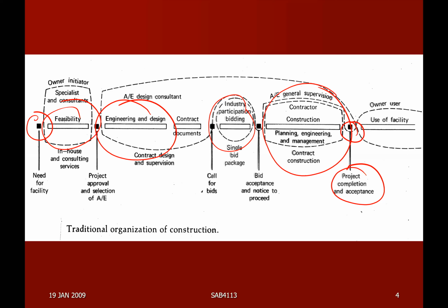So the contractor needs to come back to repair all kinds of problems, and if, for instance, the contractor fails to repair, the client can use the retention fund money, or even whatever money is being held by the client, to call another contractor to rectify those things, and later on the final payment will deduct those expenses.